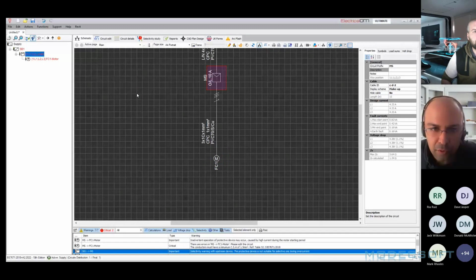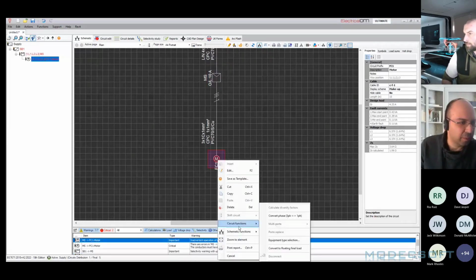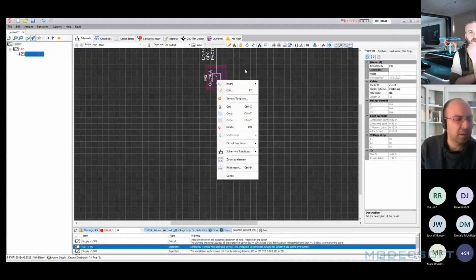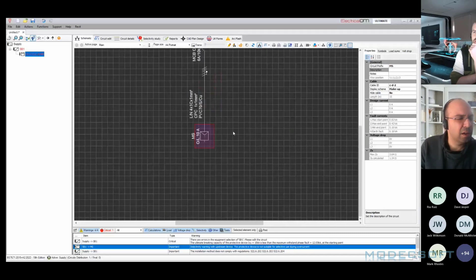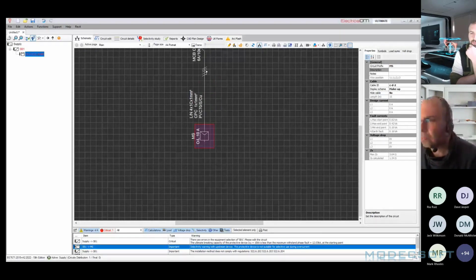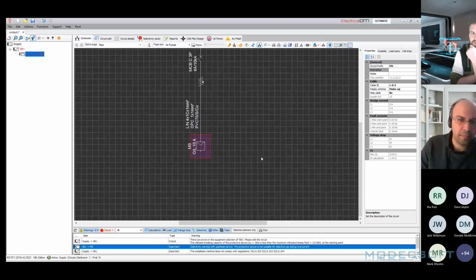The next one is you can insert a junction box after the motor starter connection. So after the motor starter, let's remove this as well. This one was added because we had lots of people asking about connections, didn't we? About having isolators closer to the motors and possibly changing conductor sizes at the rotators and these sorts of things. So yeah, maybe that's useful in that case.